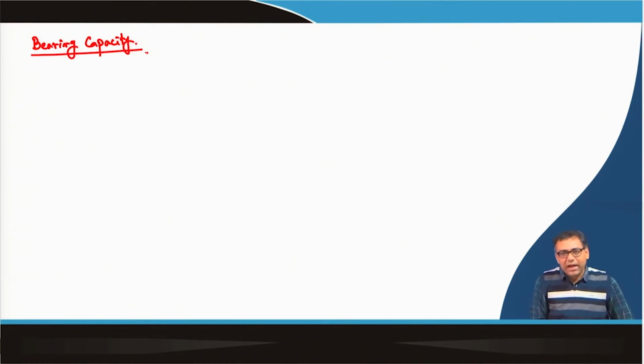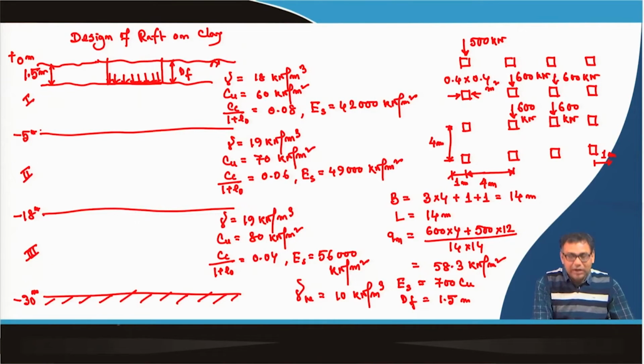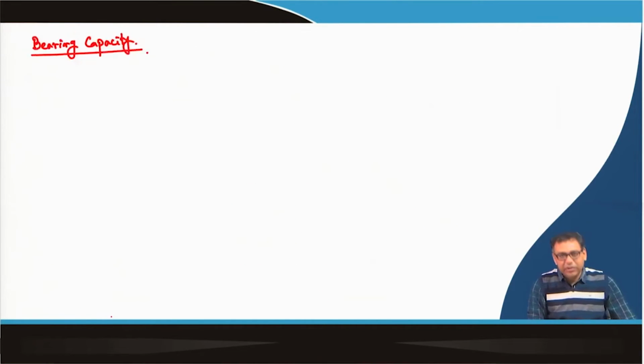Okay. So, as I have mentioned during my bearing capacity discussion for shallow foundation, it is better to use two bearing capacity equations. Here it is only clay, so I have decided I will go for the Skempton bearing capacity equation, which is applicable for only clay, because here all the layers are clayey soil. Then I will use the Hansen bearing capacity equation and then we will decide which value we will use. So, first we will use the Skempton.